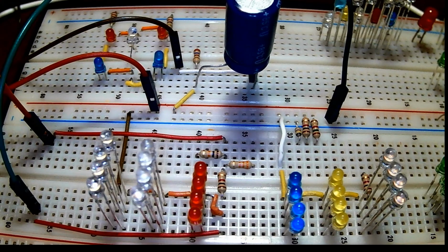One important feature is how the rate of charge and discharge can be controlled with resistance. We say resistance, not resistor, because resistor is not the only device that has resistance to a current. Virtually all devices, except for superconductors, such as inductors, LEDs, transistors, solid-state chips, even wires have current resistance. The key concept is that the higher the resistance of the path connected to a capacitor is, the lower the rate of charge and discharge will be.